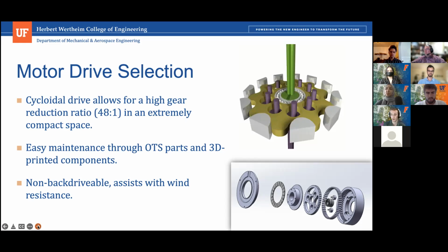Our design utilizes 3 bearings: 1 thrust bearing and 2 roller bearings. One of the roller bearings is placed inside of the cycloidal gear at an offset, like you see with the green pin in the animation on the top, and that gives the eccentric motion. The second bearing keeps the torque extract plate centered, which is the top hat looking piece in the exploded view. That torque extract plate has 6 holes in it, and those are 6 M3 holes.